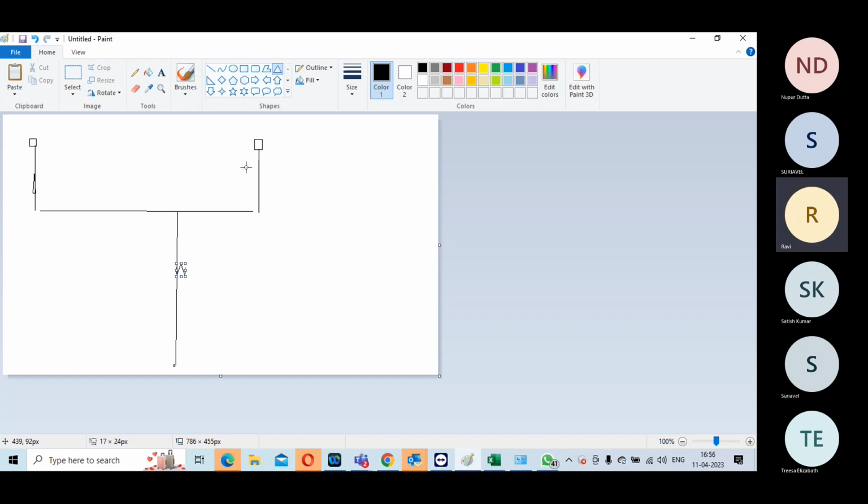All these are concepts. Before doing post CTS hold, you have to run area recovery first, then power recovery. Don't do it the other way around. You get that?